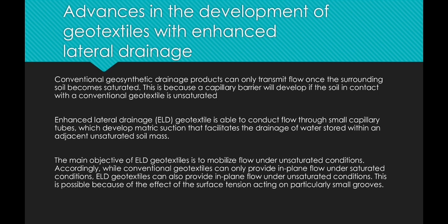Accordingly, while conventional geotextile can only provide in-plane flow under saturated conditions, ALD geotextile can also provide in-plane flow under unsaturated conditions. This is possible because of the effect of the surface tension acting on particularly small grooves.